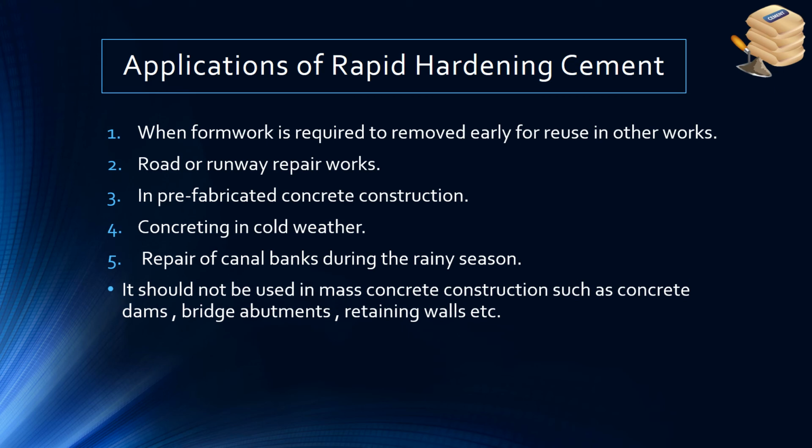It should not be used in mass concrete construction such as concrete dams, bridge abutments, retaining walls, etc., because they are liable to serious cracking due to much liberation of heat during hydration of this type of cement.